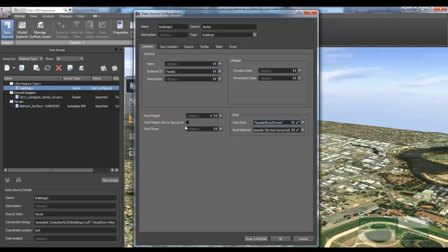Now, as part of the original tab file that held all the data for the buildings, the elevation, the height of the building had been recorded. I've got a few options here for the roof height and for the slope. In regards to the roof height, I can actually pick and tell the software to use the building height which had been picked up. That property had been picked up and stored in that tab file. In regards to the roof slope, I'm just going to pick 22,